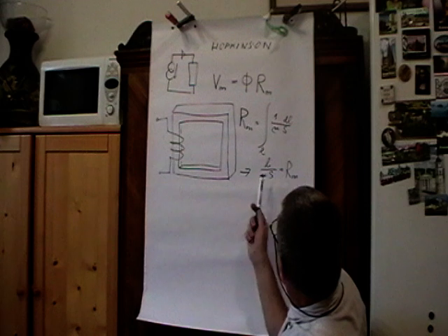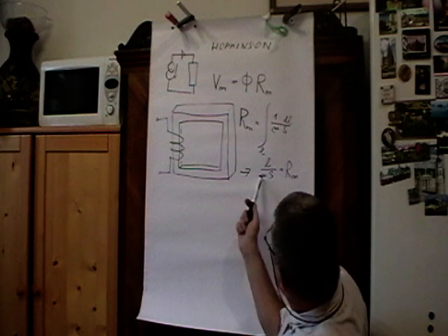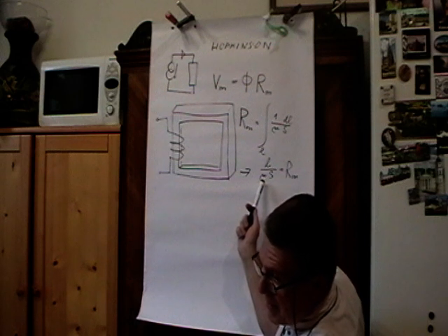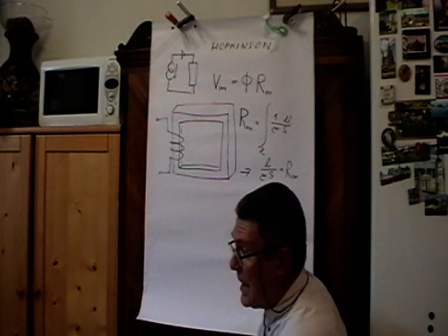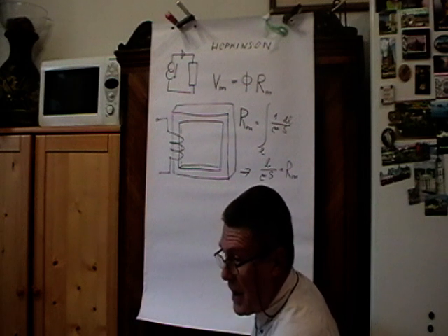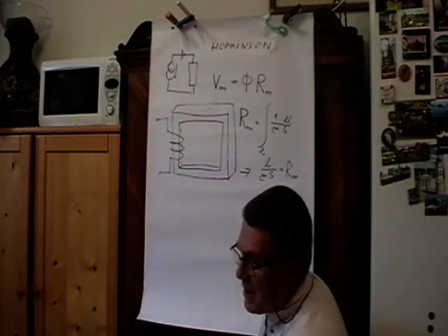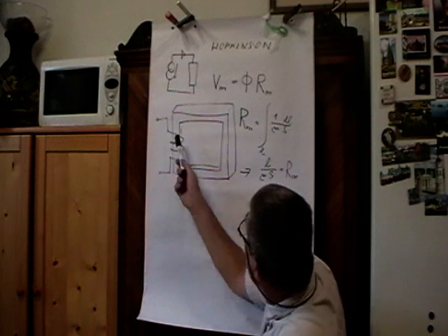It resembles a simple equation determining the resistance of an electric conductor. Just you would substitute simple resistance and specific conductivity of the material here. So it's quite a simple case. It's quite similar to an electric circuit. Now if we have this, we will possibly be able to determine the total reluctance of this magnetic core.